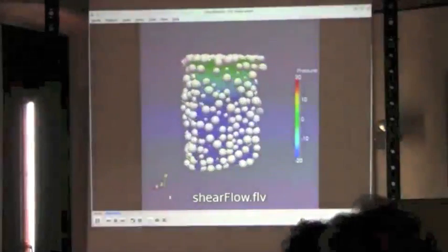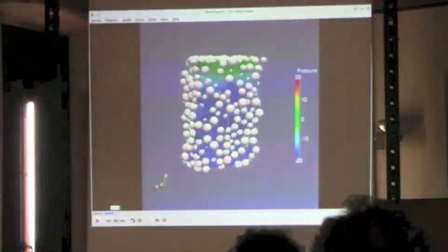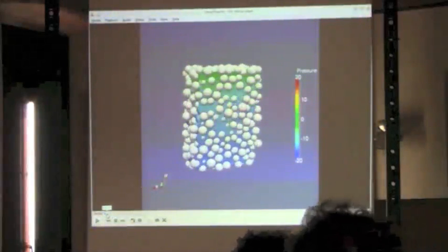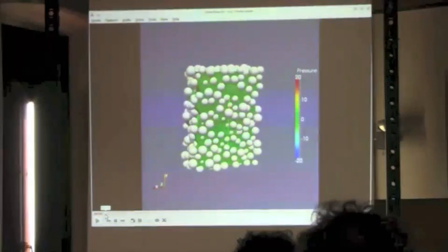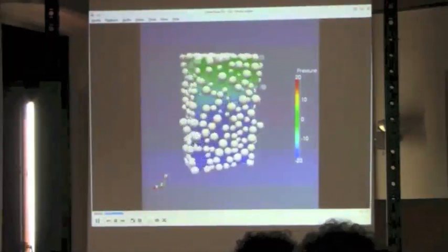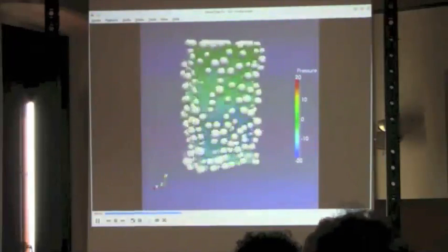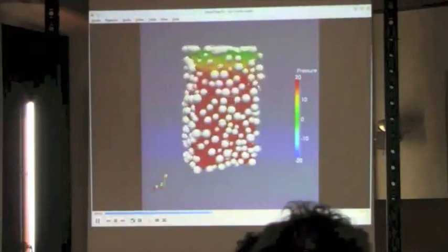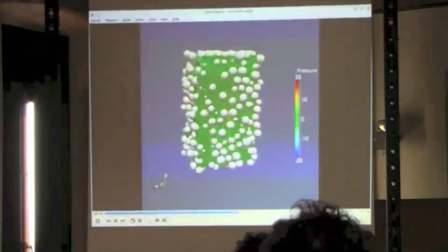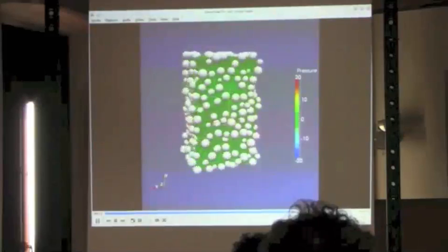This is the sample. Okay, so periodic boundary conditions, let me go back. It will start from the very beginning, pressure equals 0. Red will be excess pore pressure, blue will be negative pressure. Initially you have the latency, so negative pore pressure, blue. After that I accelerate, so it's blue again. And then I slow down, positive pore pressure. I have a transient liquefaction phenomenon as soon as I slow down the motion.